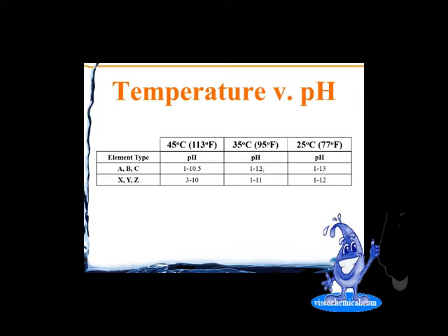And chemical cleaning does take life off the membrane. The more aggressive the cleaning, the more life. So here's just an example. This is actually a Dow example where they'll tell you that there are different types of RO membrane, that if you want to go to the highest temperature, you're going to have to limit the high pH to 10.5.